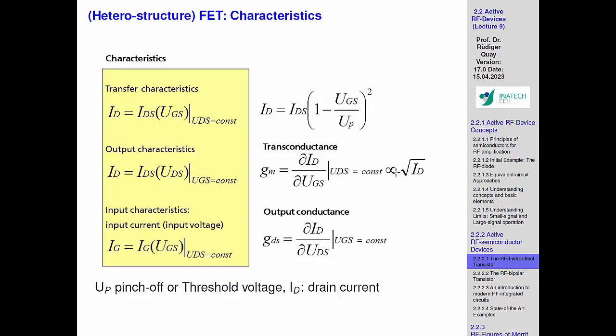And the other thing is, what we don't want is that the output current changes with the output voltage, because the transistor principle is always GM forward divided by GDS. If you have GDS very low, so that the current is not changing, then you get a good gain.